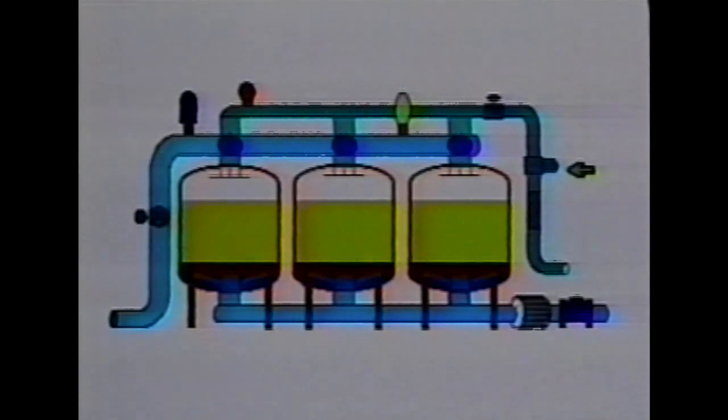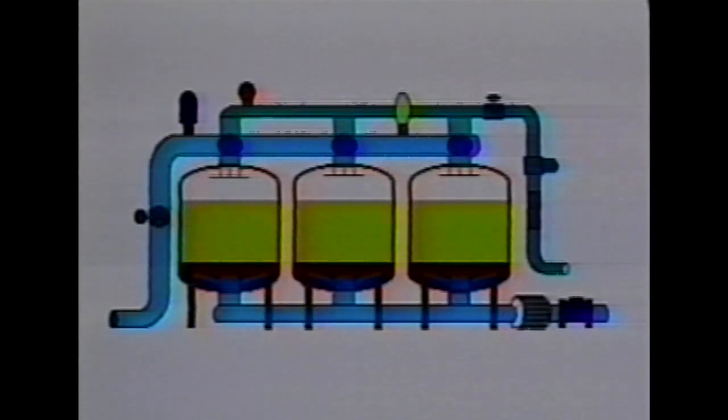There are 2 types of sighting glasses in the backflush line. One is a specially designed sighting and sampling port, which continually passes a portion of the backflush flow through a small attached glass jar which allows an operator to see if sand is passing by.